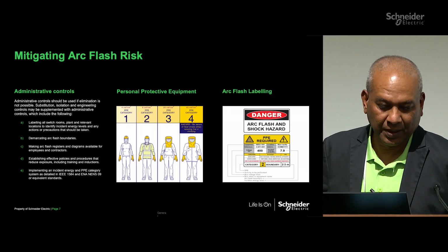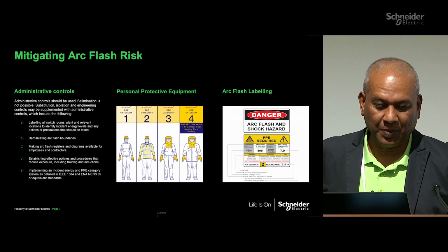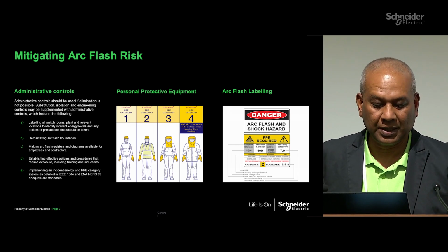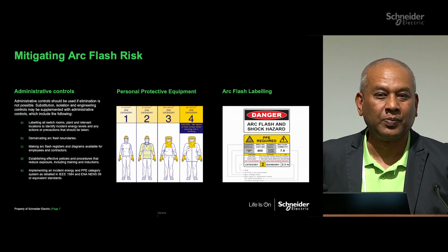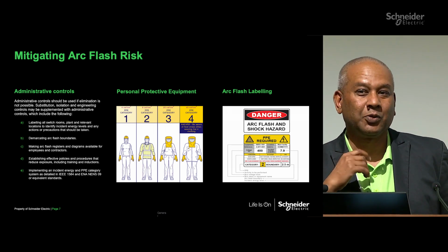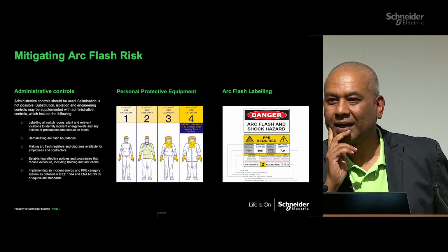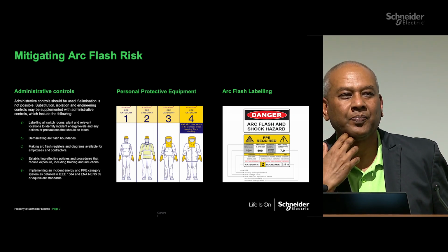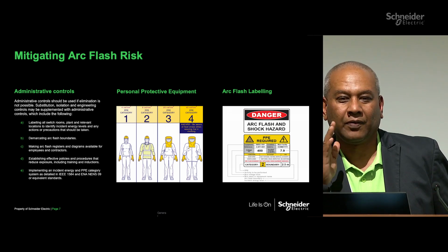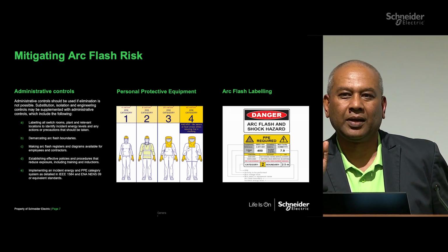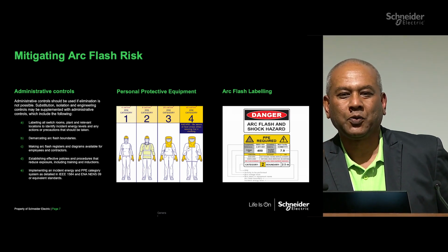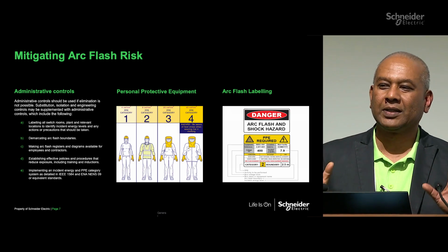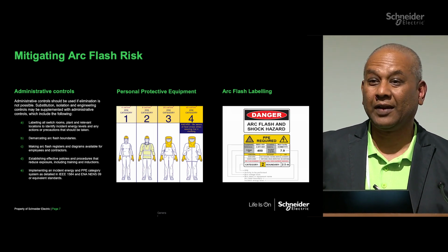Once you have found the arc flash category, either by guideline or by calculation, whatever PPE is recommended, you should comply with wearing that PPE. One other thing: modern equipment is all internal arc rated, and we specify criteria such as front, lateral and rear arc flash protection. That holds true provided the equipment is in its normal operating condition, so no covers are open, no doors are open, even LV doors.